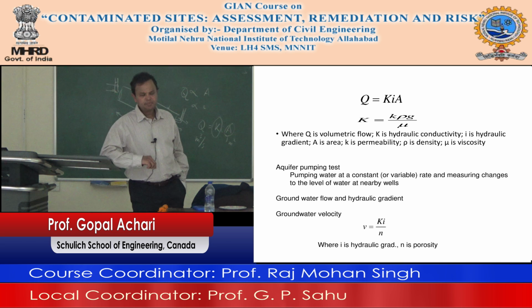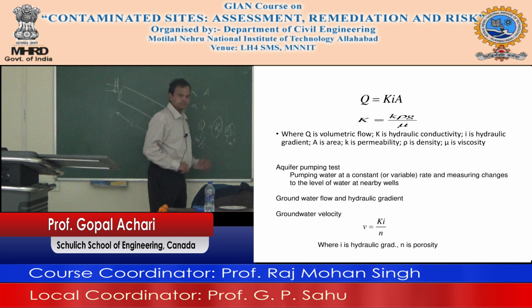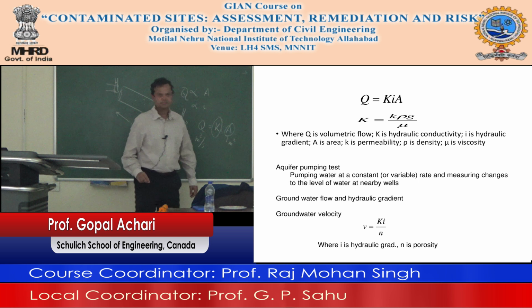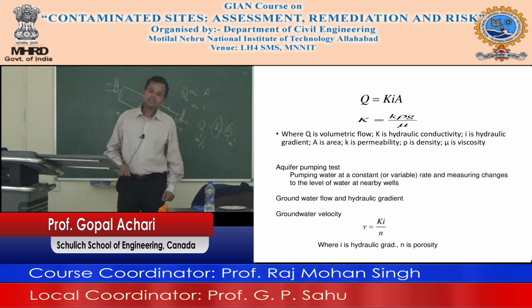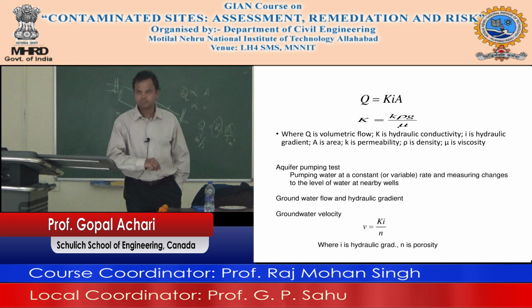The seepage velocity is given as K times I divided by N, which is the porosity, and that is the average velocity with which water flows in the pores.